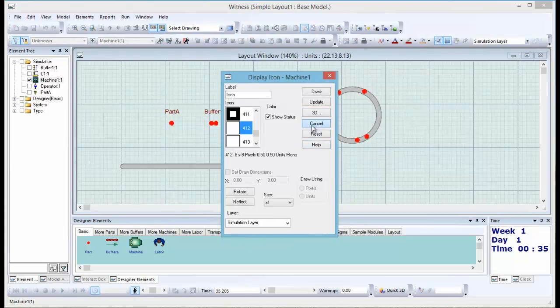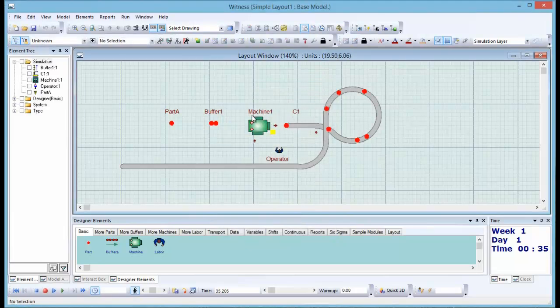If none of the icons for a machine have a 3D representation, in other words, if you said all the icons are displayed to be no 3D representation, or indeed you have no icons displayed for the machine at all, then instead of linking an icon to where the part will be positioned, the part Q position is taken as the position for where the parts will be shown in the 3D view.